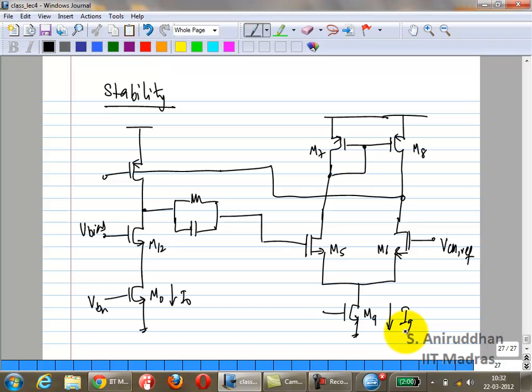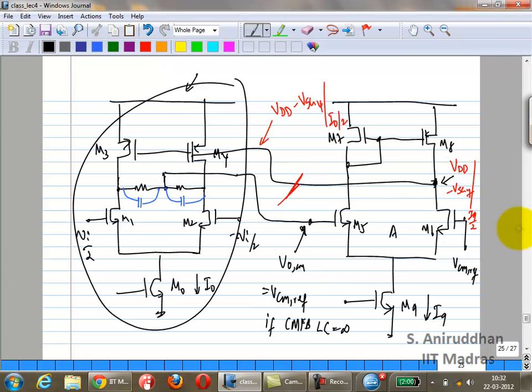Which is 14? So if you have a differential circuit and you want a common mode picture, what do you do? We just fold over the differential part. If you don't remember, that means you should go read it. You should go study it. But that's what we do. So you fold over the differential part and analyze the common mode picture.